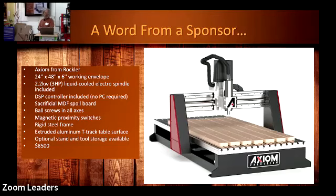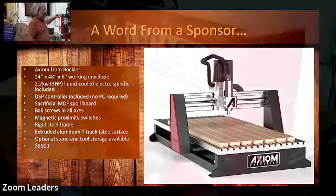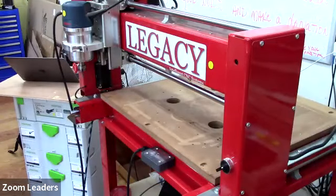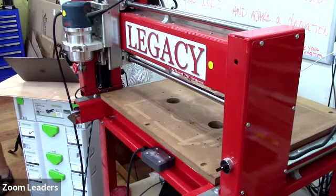They use ball screws, which is typical for a mid-range machine. These magnetic proximity switches are installed in the machine at the terminus of the motion of the machine. It's so that if you're running the machine, it doesn't slam into the end. The proximity switches should tell the software, hey, you're at the end of the line, stop moving.